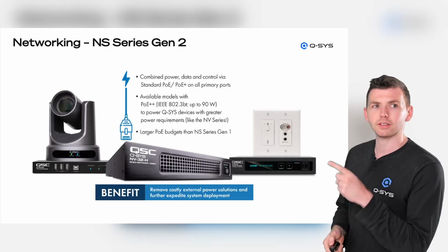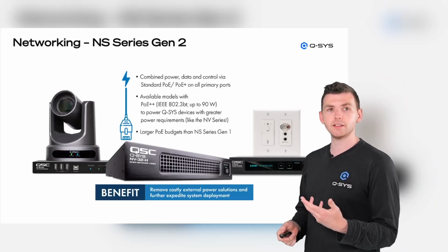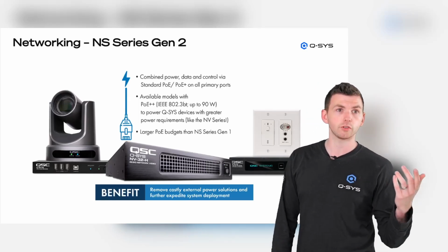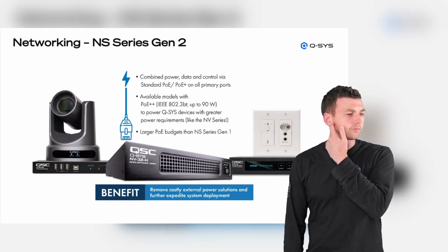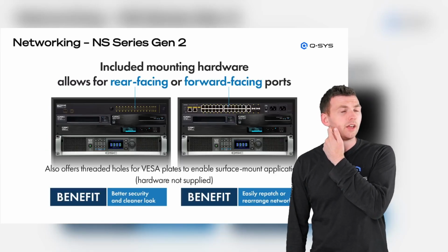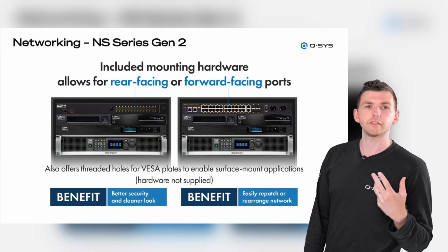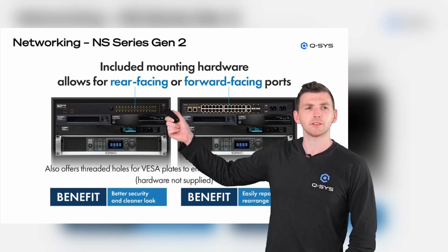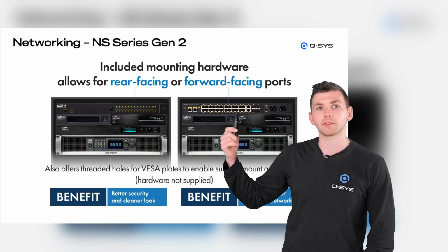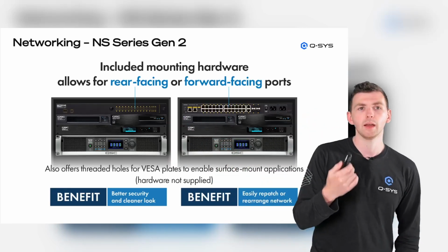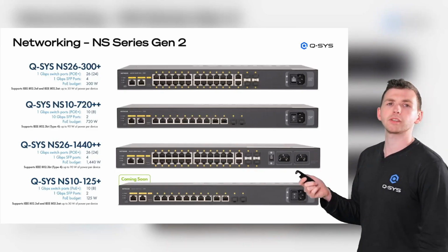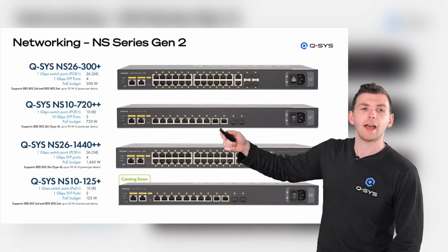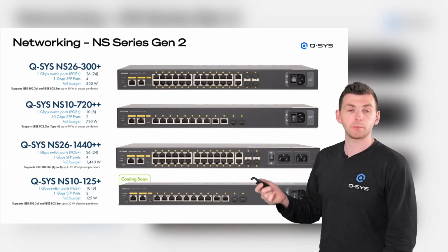So that PoE++ is great. You can get these switches with 90 watt on every port, which means you could have a lot of NV32s, or of course NV21. And another nice thing, just physically, these come by default with rear-facing ports. So your AV rack with all the AV devices with ports on the back just all lines up, looks very good. Or you can mount it the other way if you want to. And when you're choosing these, it basically comes down to the number of ports you want. Do you want 8 or 24 ports? And do you want PoE Plus or PoE++?